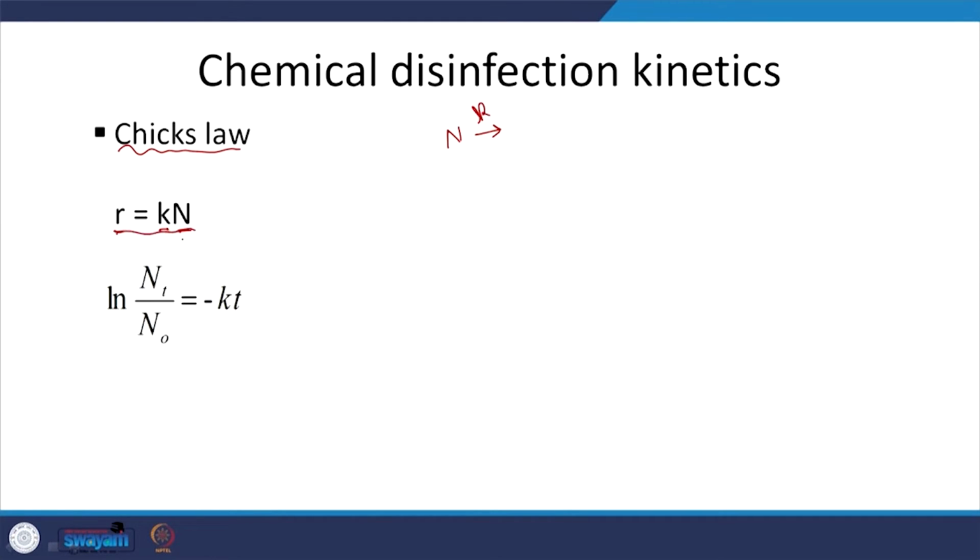So, if you put that into a batch system, you know what the mass balance is: V dC by dt is equal to Q in C in minus Q out C out, this is out, not plus, plus volume times rate of formation minus rate of loss of that particular compound.